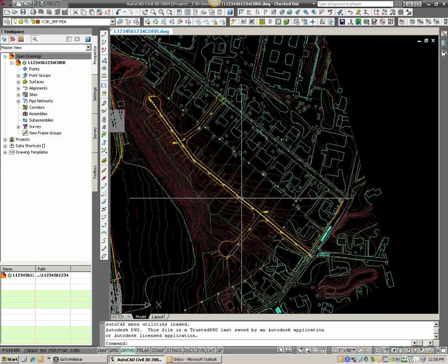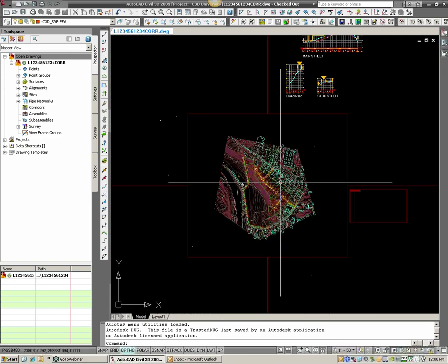And the reason you want to do that is because once you start into that scalpel stage, if you make major changes in the road profile elevations, you're going to be redoing work. Civil 3D is not dynamic, so that everything will just automatically update if you change your road profile up and down 50 feet, that all the lots will regrade themselves. It doesn't work like that. You'll have to go back and redo work still. So we want to get those major changes out of the way up front. And then once we go in with our scalpel or our steak knife, we don't have to worry about those, and we're not wasting any time or doing any redo work. So let's go ahead and figure out how to do this.